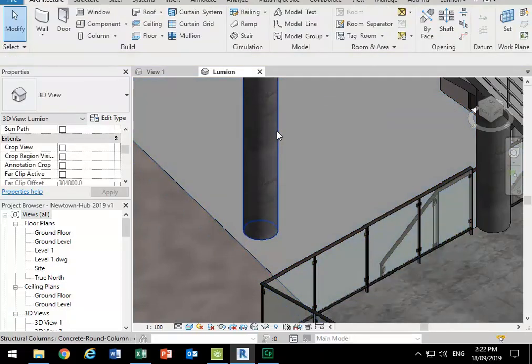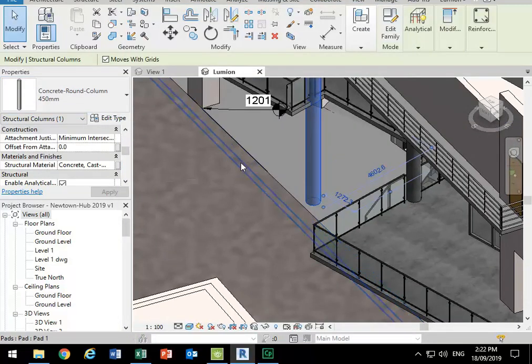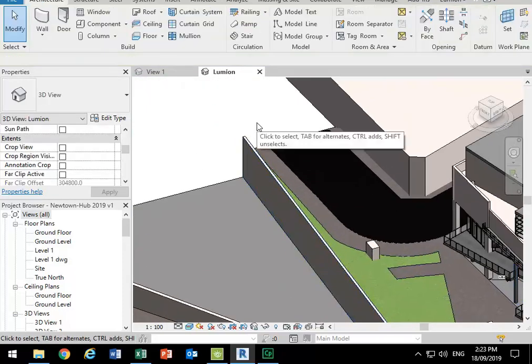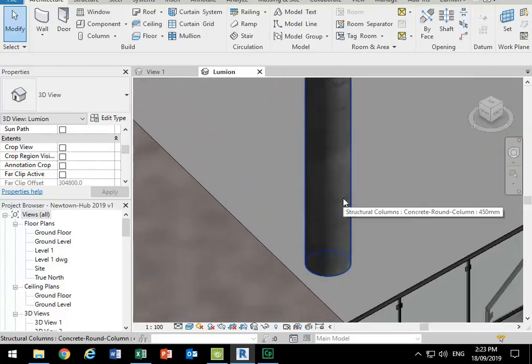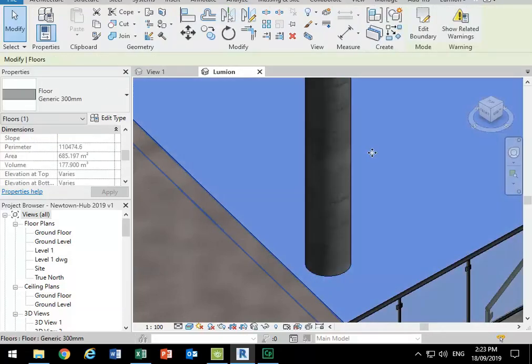No, not at all. If it's using a texture, it ignores that for rendering. Yeah. Okay, so that's something that will definitely help you, particularly as you go further and do more with your own textures. And then again, don't forget that you can do a lot of the work to change the way textures work and appear by working in Photoshop, rather than doing a lot of the work in the material settings in Revit.